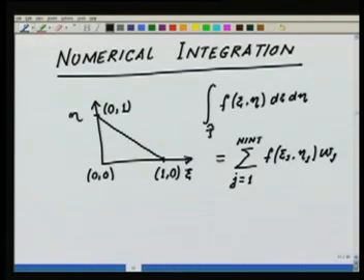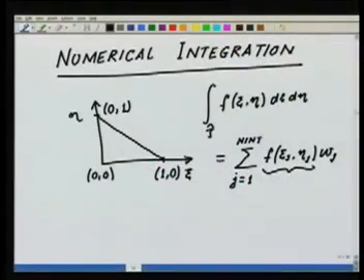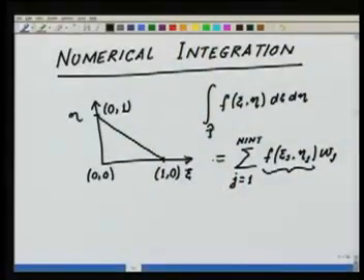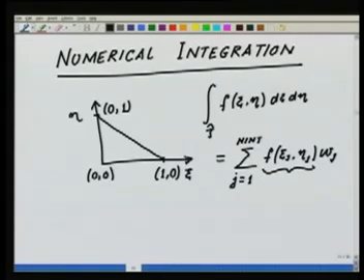So now the question is that depending on the order of the integrand, remember we are dealing with polynomials only here, defined over the master element, the polynomial order will define what order integration rule I should use and how many points would give me an exact integral for that given order. So the number of points is fixed by the order of the integrand.